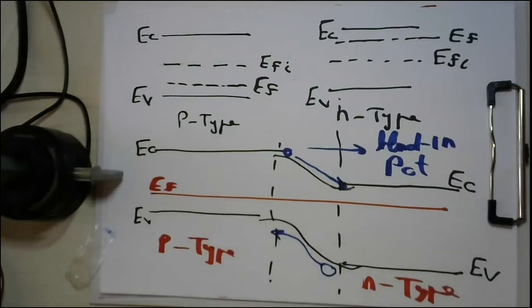So when you have any semiconductor device or junction, I told you, please check if this junction is under thermodynamic equilibrium or not. What you are going to do simply is to check the condition of the Fermi level. Is the Fermi level flat or not? If the Fermi level is flat, then the material or the junction is under thermodynamic equilibrium. So this is simply the first observation.